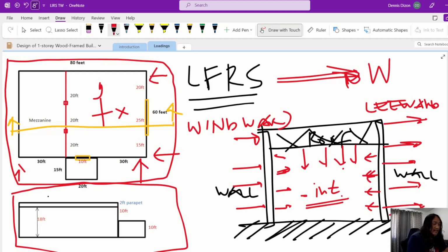So it will just cancel out. This internal pressure going away from the wall, and then this also away from the wall, they are canceling it out. They are in opposite directions, with the same value, because the internal wind pressure is the same value all throughout the interior of your structure. That's why internal pressure is not considered when calculating for the primary structure like the whole building.